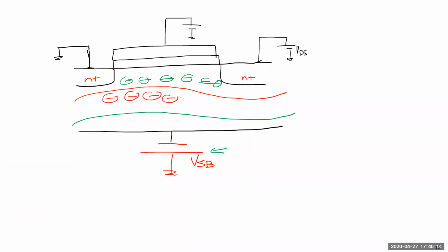So you're saying, if my depletion is looking like this, then this phi must be at a higher voltage, not at a lower voltage. But this charge has not come because of your gate. This charge has come from this. In order to get this phi s such that the depletion looks right from VG, you have to increase it by that amount, and that's the potential you require on the gate side.